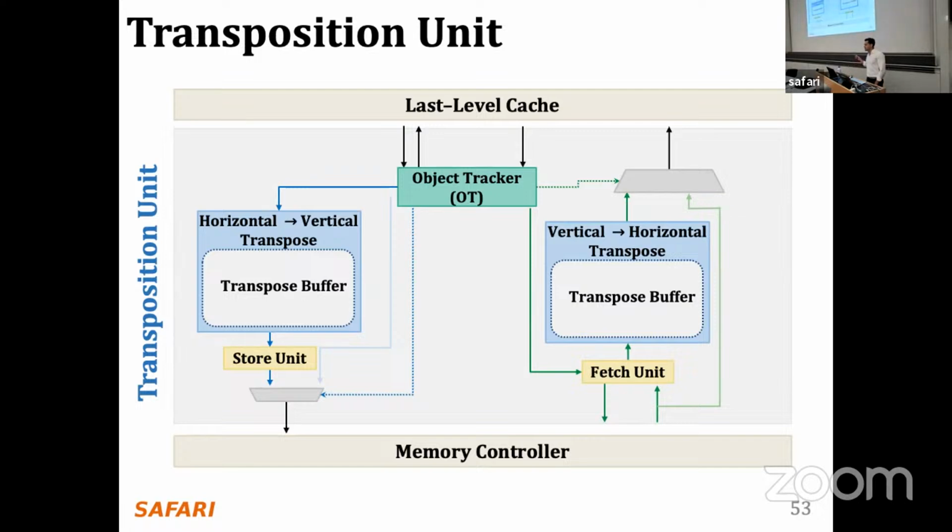So I was not clear because I didn't give the sequence for the ripple carry adder. But basically, since I know that that bit is going to be used both for carry and for the sum, once I compute, I also copy to a temporary row, so that I can use it later and don't destruct the bit for the sum. Essentially, we move A and B to the computing area: B is only moved once, A needs to be moved twice because of how the circuitry is designed.